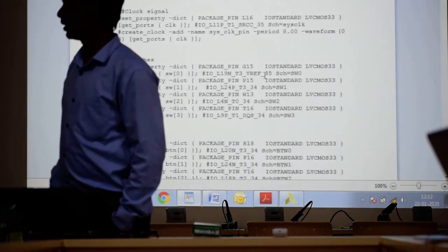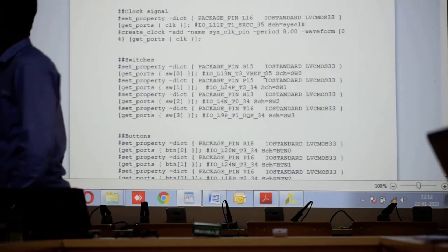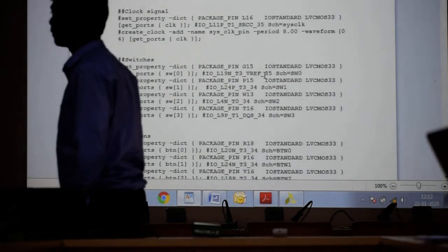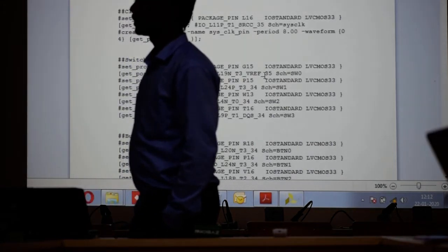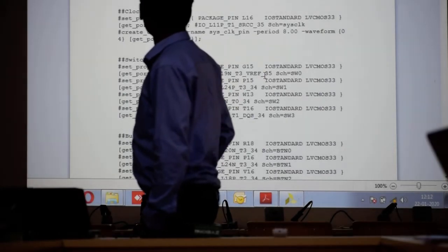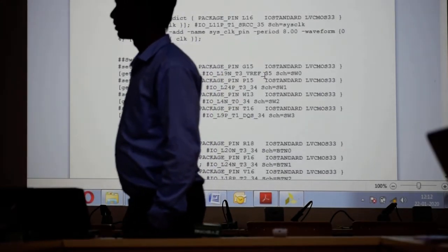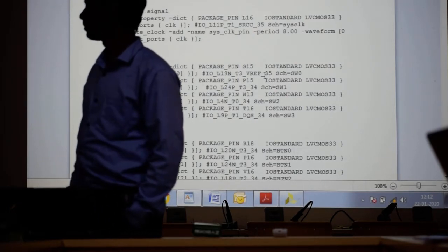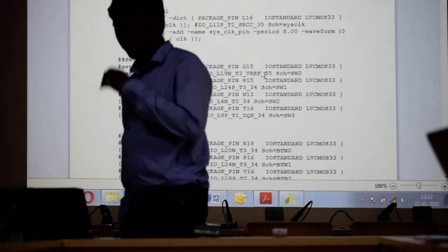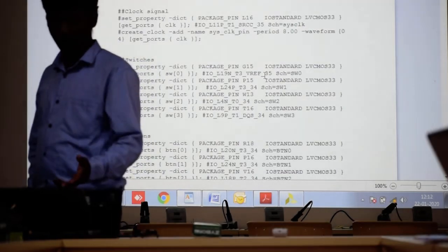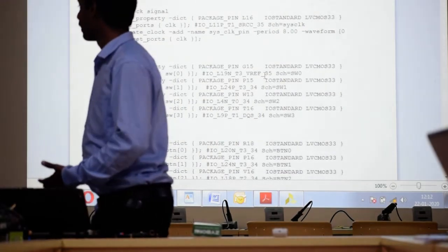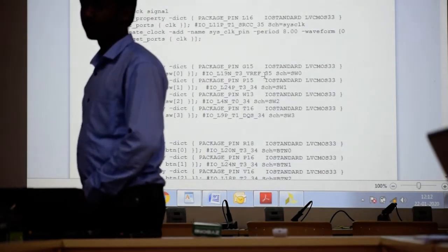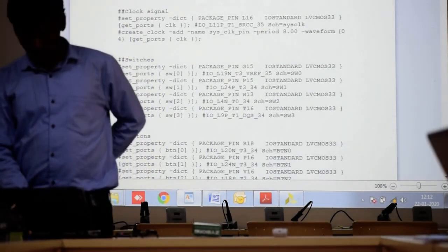So you can see the file and you need to understand. You can Google a pin configuration file for ZYNQ Z7. You will get that file. You have to Google it. So you get a file like this, where you can know what the clock pin number is, what the IO standards are. It will be on GitHub also. This file is available.